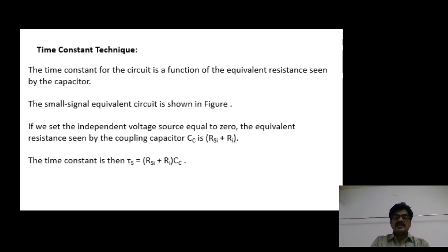Another analysis, what I said, is time constant analysis. Whatever we have seen previously is current-voltage analysis. Now the time constant analysis. In the time constant analysis, you can directly write the time constant by observing the small signal equivalent circuit.